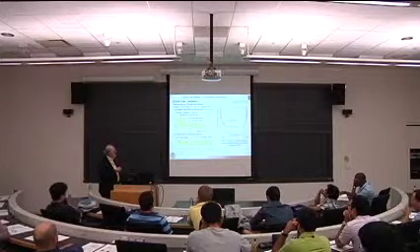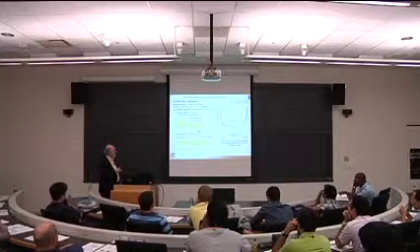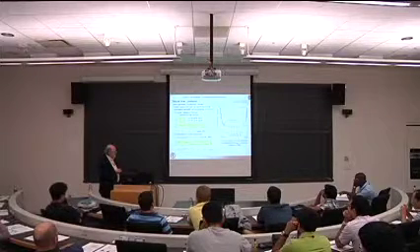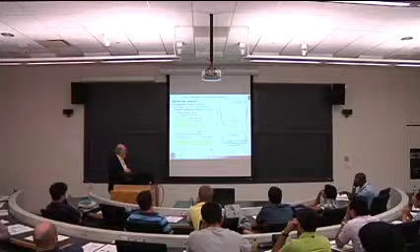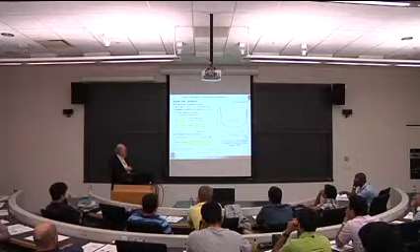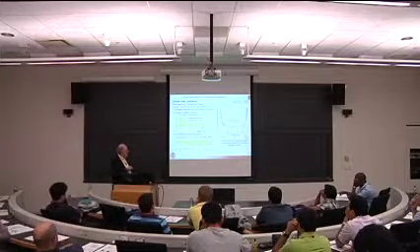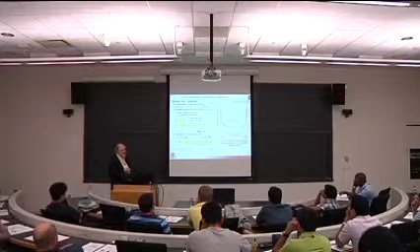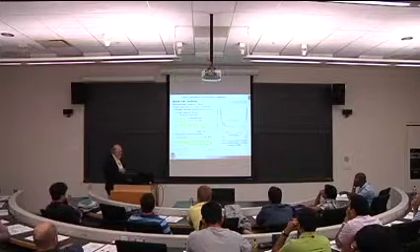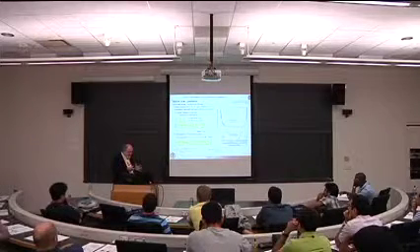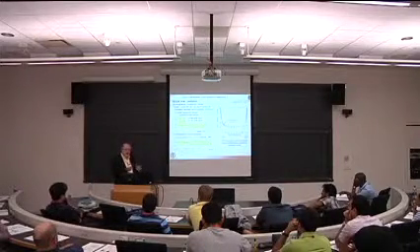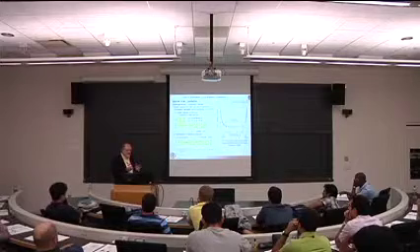And this plot here just shows experimental data of the sound speed as a function of the void fraction. You have high sound speeds if you have a pure liquid, and of course lower than in a liquid if you have pure vapor. And then somewhere in between you see a real reduction in sound speed. That's because when you have bubbles in a flow, those bubbles basically act like you had a pliable wall in your duct because they're compressible.